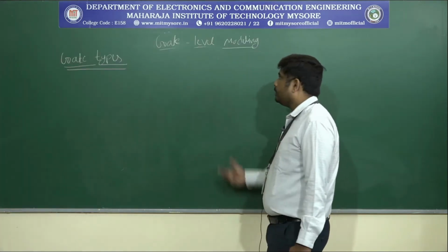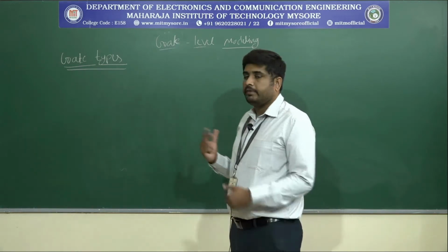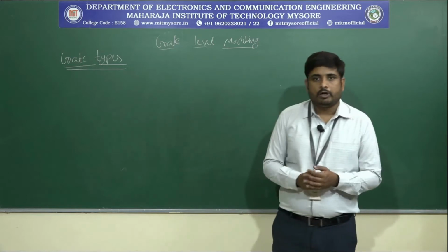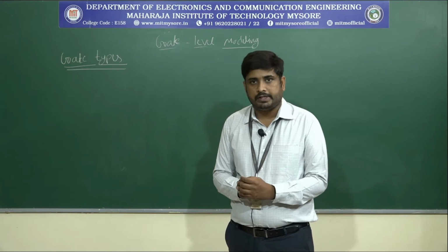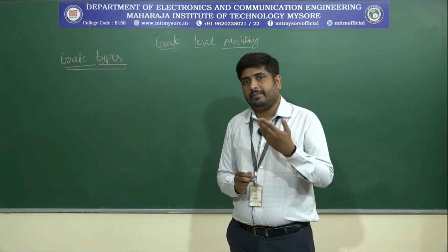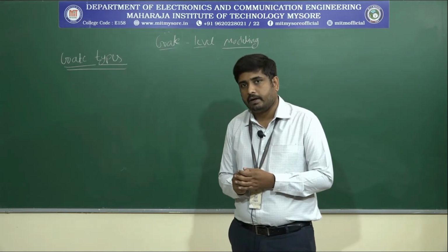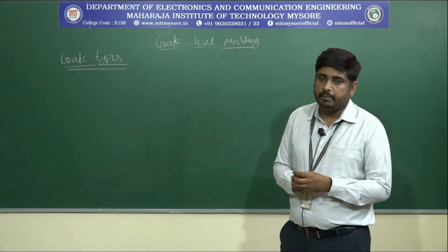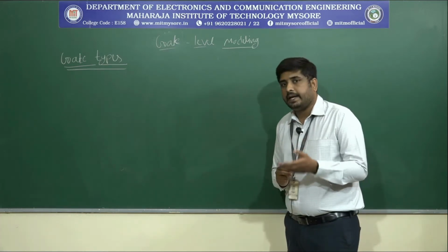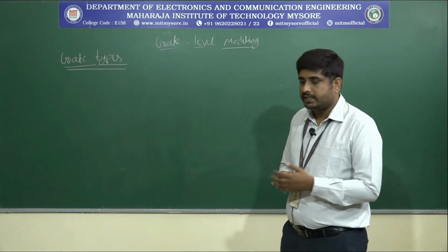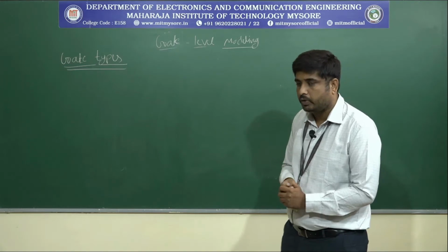The first topic for gate level modeling is gate types. Usually we know that a logic circuit can be designed using basic logic gates only. It may be a mux, a full adder or a half adder, which can be designed using basic gates, right? The basic gates we usually classify into two types. That is, gate types can be classified into two types.